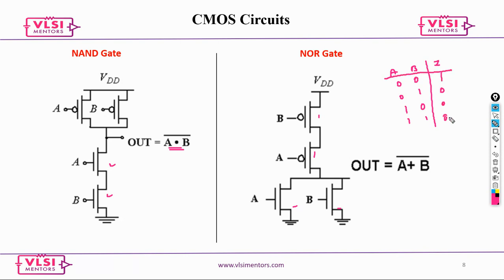Okay, great. Now let's talk about the first scenario. What is going to happen to your transistors on the PMOS side? Both A is on, this is also on. So there is a direct path, a charging path, so likely the output would be 1. Now, what about your pull down? This is going to be off, and this is off. So your answer is verified for the one case.